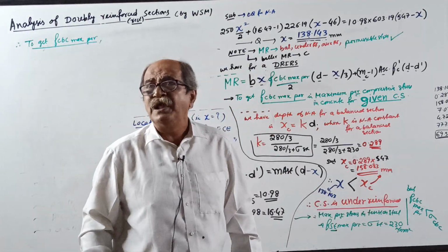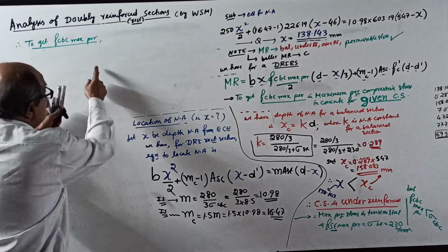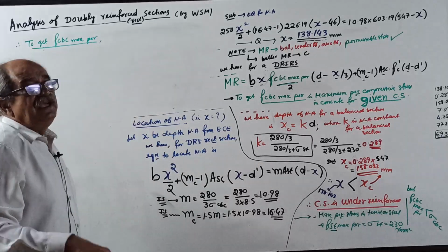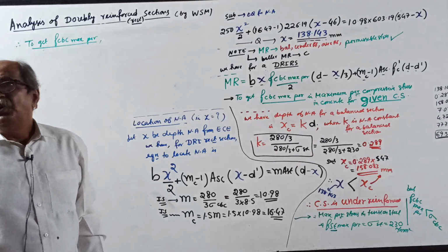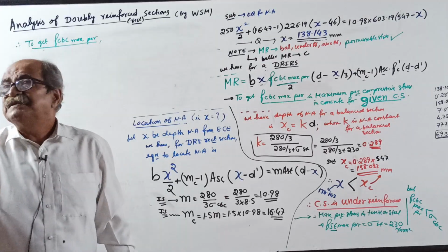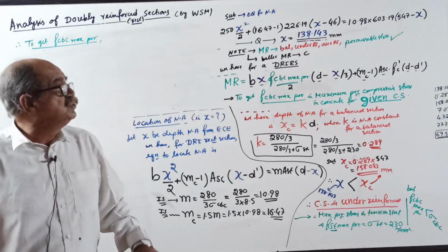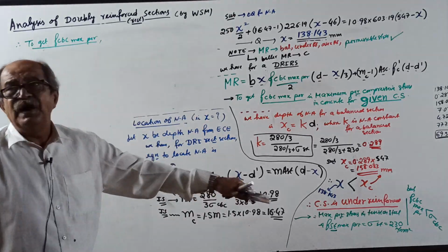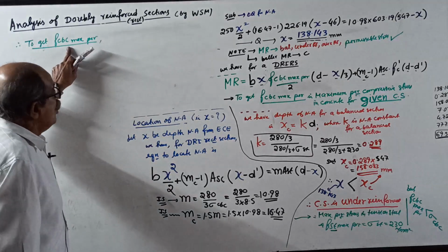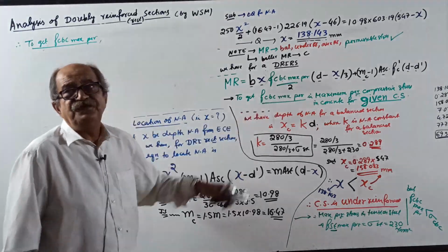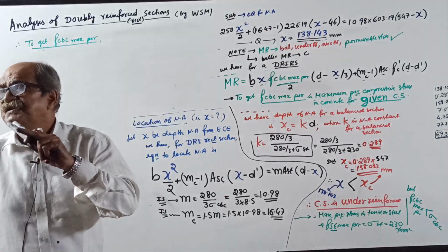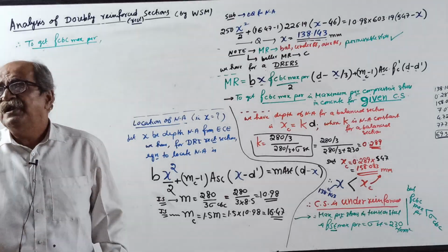Or write the statement: maximum permissible stress in concrete is that particular value when stress in steel reaches its limit. Surely that value is less than sigma CBC. By chance, if you use stress in concrete equal to sigma CBC of 8.5 Newton per mm square, then stress in steel will go beyond the limit, unsafe.